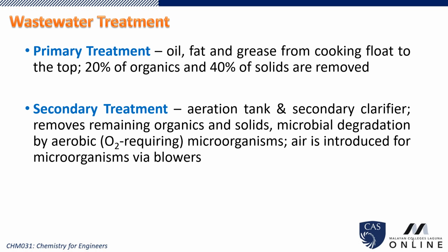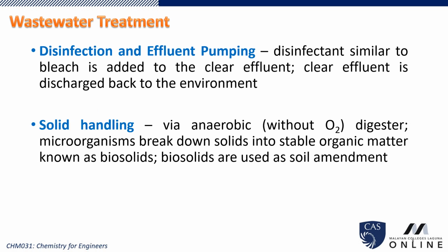Secondary treatment uses aerobic microorganisms to break down organic matter. The air is supplied using blowers, and bacteria use oxygen to degrade organic pollutants. This process removes up to 90% of biodegradable waste.